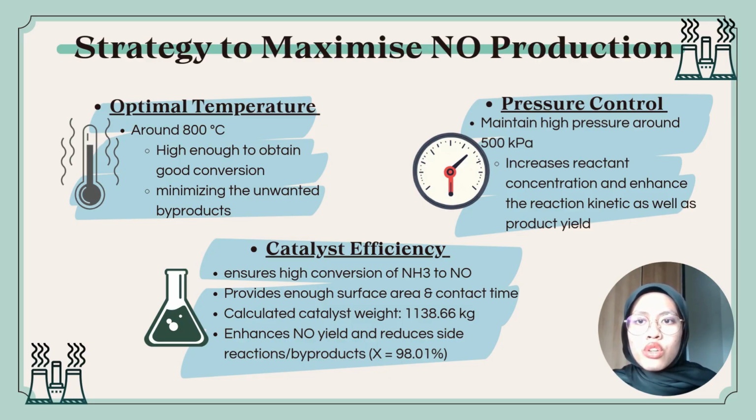Next, pressure control. The reaction will be maintained at a high pressure, approximately 500 kPa, to increase the reactant concentration in the reactor as well as improve the reaction kinetics and produce a higher product yield.